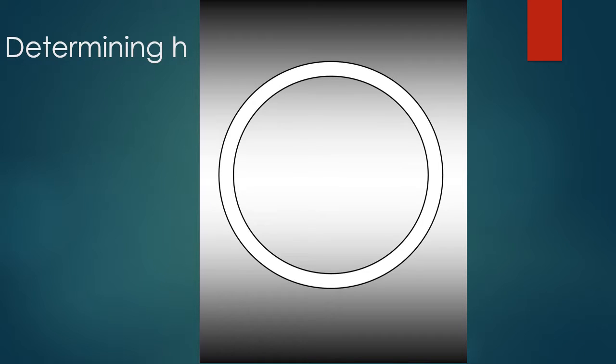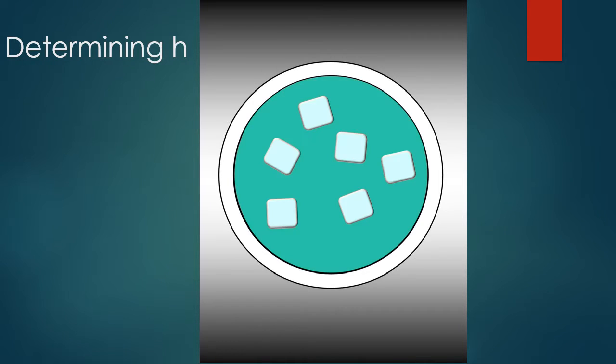To experimentally determine our H value, we first selected a PVC pipe, which we then filled with ice water. Because we know that liquid undergoing a phase change is at a constant temperature, this will allow us to achieve steady state conditions. An assumption that we made is that the surface in direct contact with the water at steady state conditions is equal to that of the water.